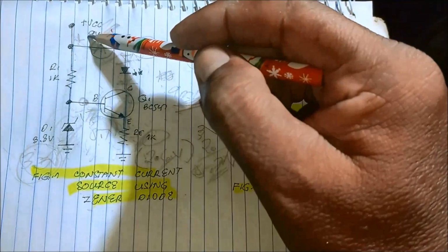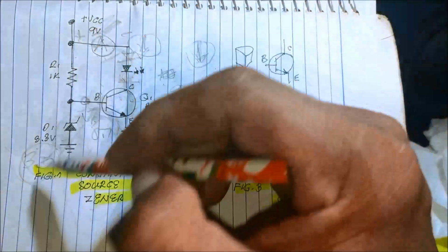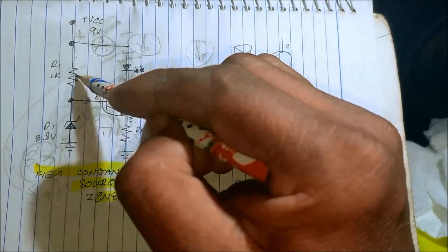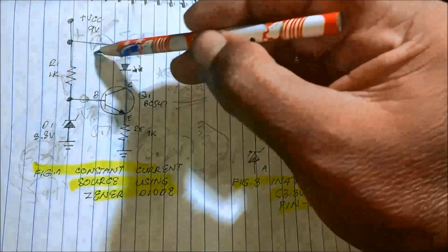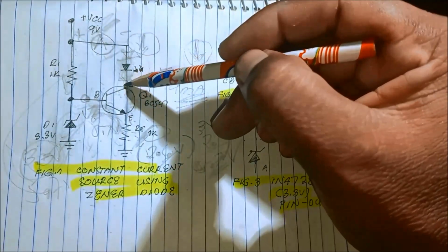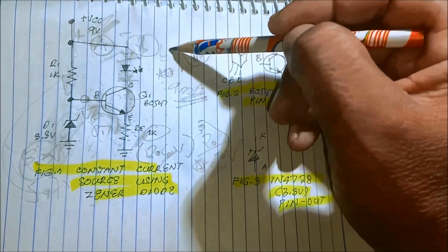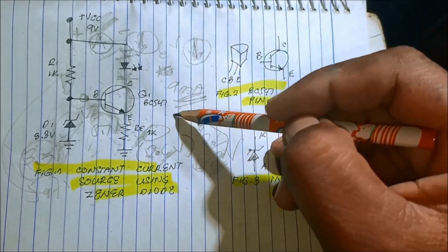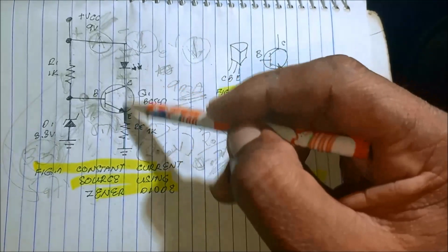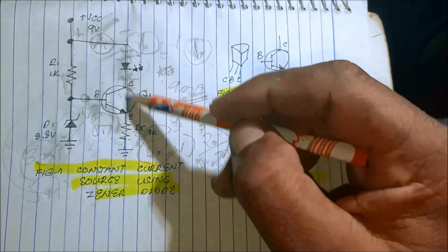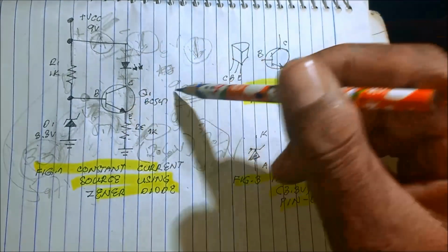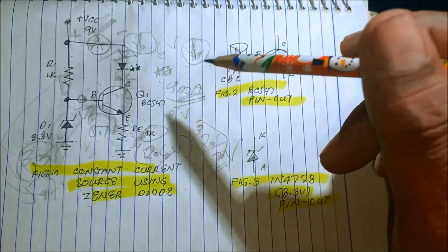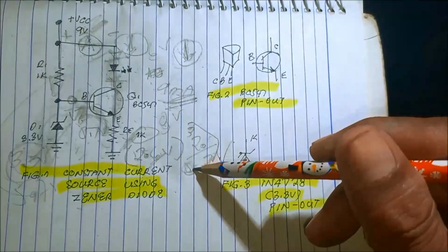Remember that if we have 9 volts here, if we have 3.3 volts here, we have 9 minus 3.3 volts is 5.7 volts across the 1K. But at the output, if we have 9 volts here, if we have 3 LEDs here, 2, 4, 6, 6 volts for the LED, plus the 2 volts at the emitter resistor, it is 8 volts. And the remaining will be dissipated across collector to emitter, making this serve as an amplifier and then eventually become serving as a switch. Okay?